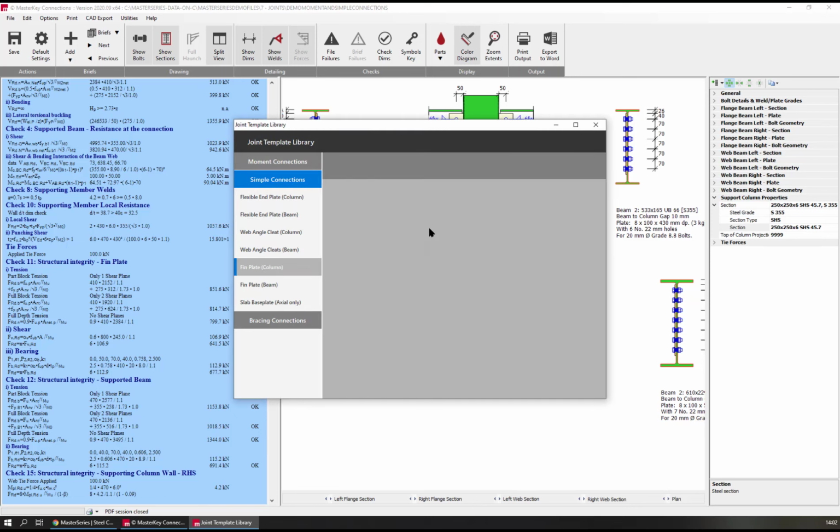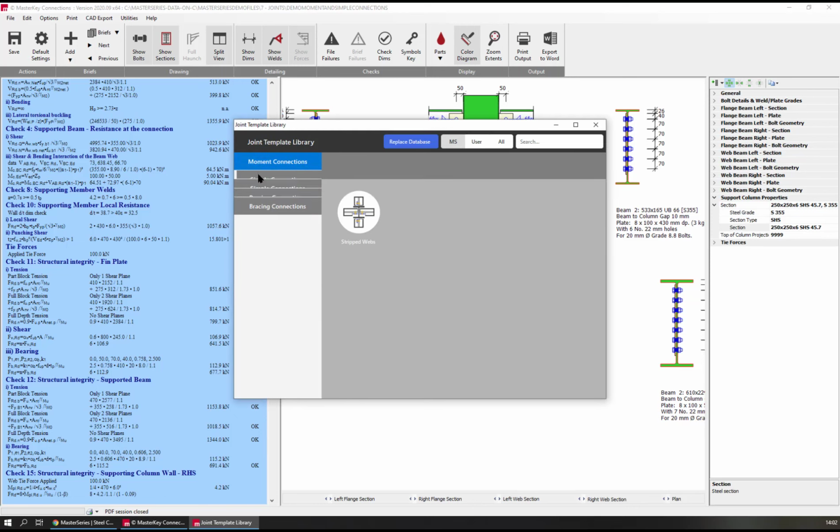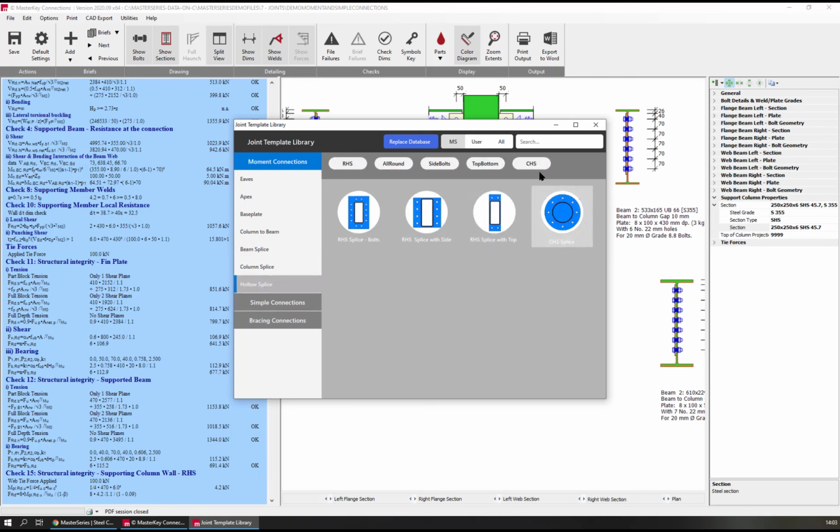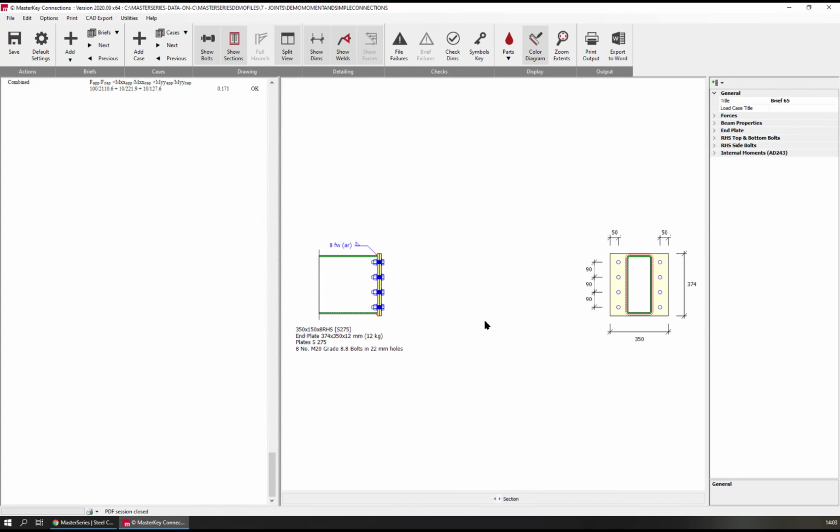The other hollow section that we can do very, very well is the hollow splice, and I'll just take one of these to emphasize. So we can do a hollow section type apex splice, what I would call a pipe flange connection, and we can have plate above and below with bolts, or just to the sides, or just to the top.